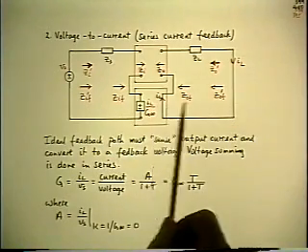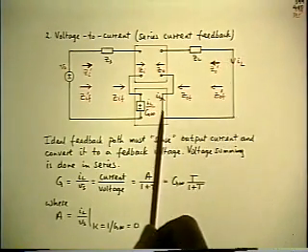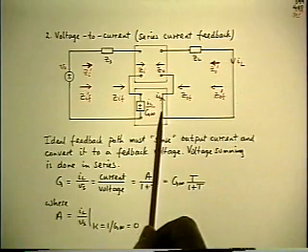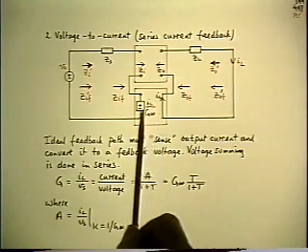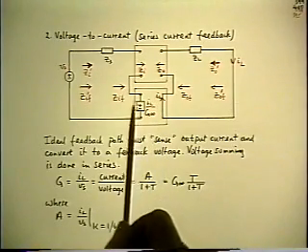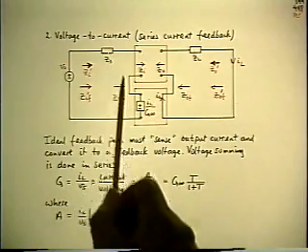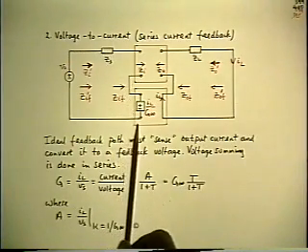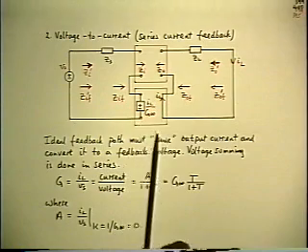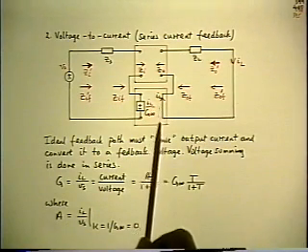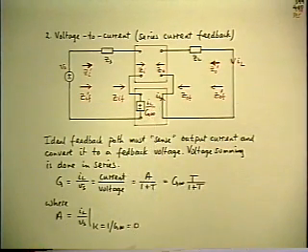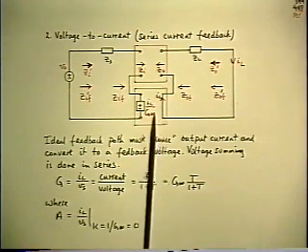So now you sense the output current IL by connecting the feedback box in series and sensing the current. The feedback box then converts that sensed current into a fedback voltage, which again is differenced with the input signal by the series opposition connection. So this is the standard current sensing, and ideally you want to sense the current with a zero impedance. In practice, you do it by a very small resistance, an ohm or a fraction of an ohm, or you can do it by a current transformer.